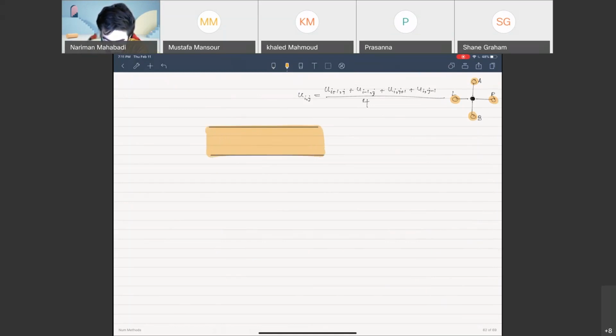We're gonna fill some tube with soil, apply some total pressure on one hand, and then release the water from the other hand and see what would be the velocity or permeability of the system. So let's say in this case, I'm gonna connect the left boundary to a tube, and then I'm gonna fill this with water up to some special point.